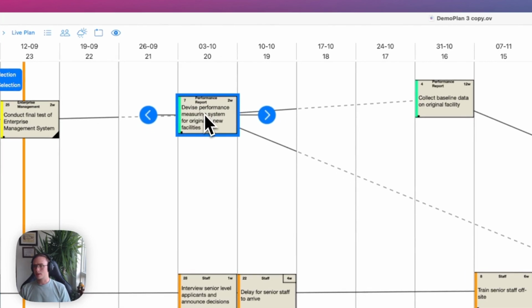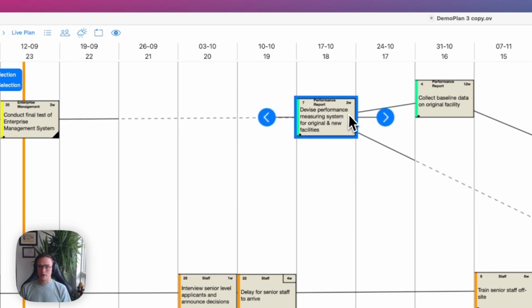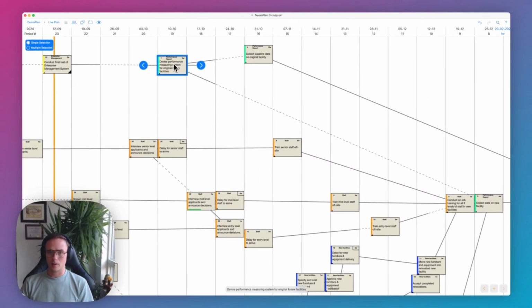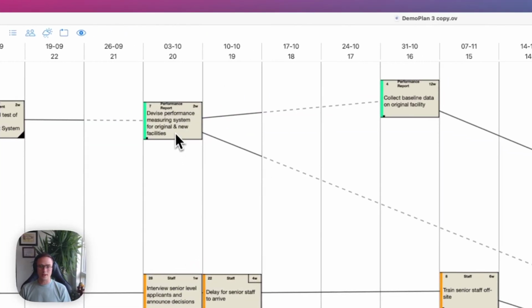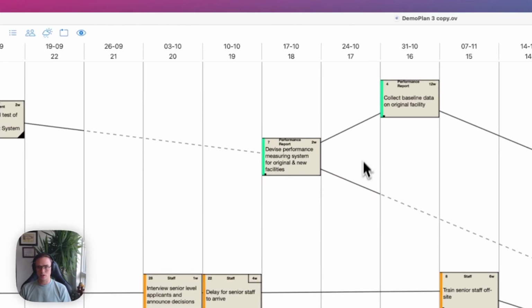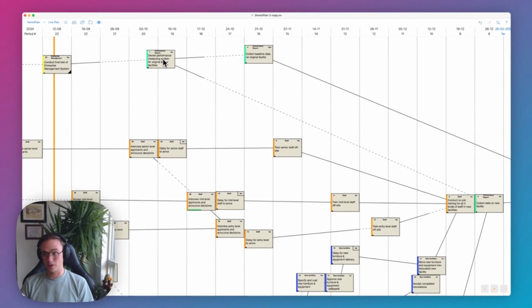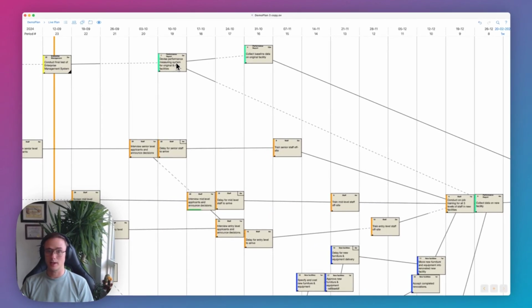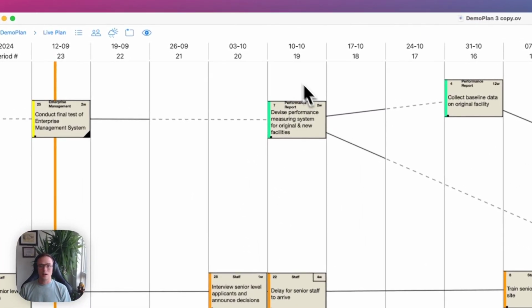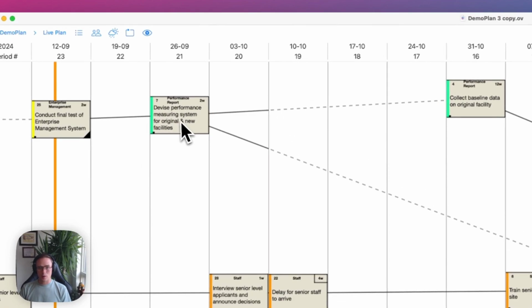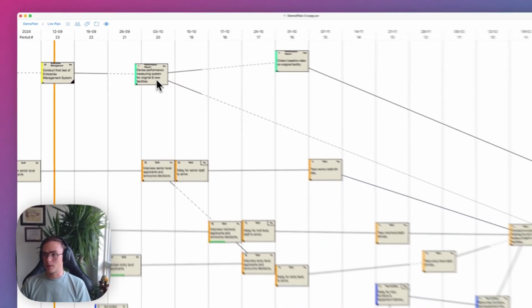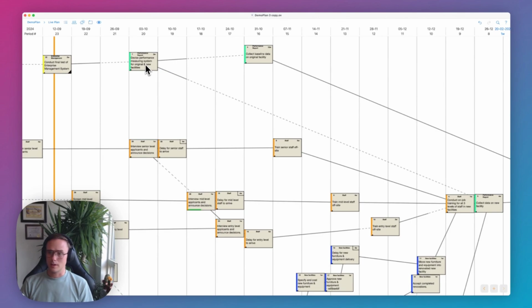So this is very important when things change and you're overdue on a certain task. What are you going to do with that task? Are you going to throw more resources at it? Are you going to change the float? This is a very easy and dynamic way to visualize how you can make those changes on a day-to-day basis. So again, I'm not changing the duration of the task. I'm just manipulating the start date of the task, as well as the float, drag or slack, if you will.